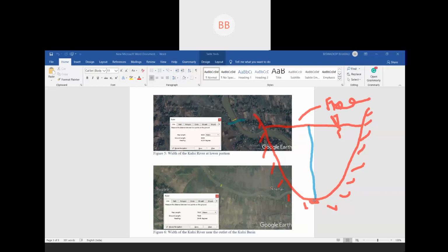As you can see, at the bottom level your friction is more with the bottom of the channel. So here, at the bottom of the channel, we consider the velocity is zero. And from zero, when we move upward, it increases.